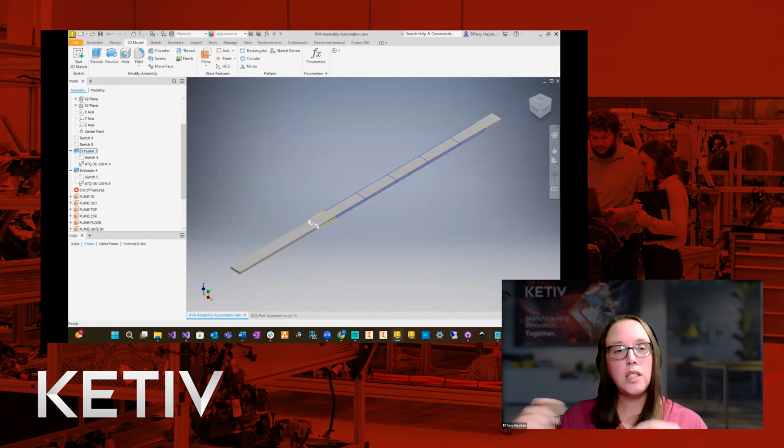If you ever run into a situation where you're removing all of the participants from the extrusion cut, the cut actually disappears. That's not a bad thing, but if you're dealing with this on a programming level, it can be very hard to have to recreate that cut every time.